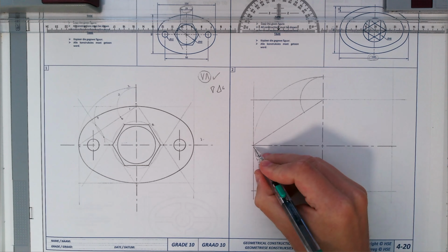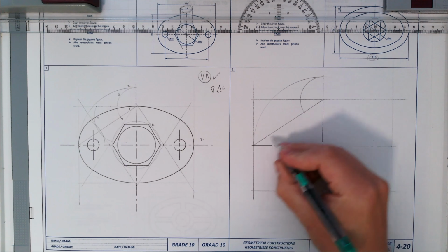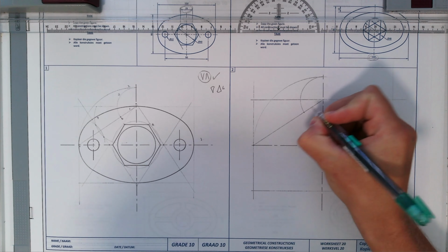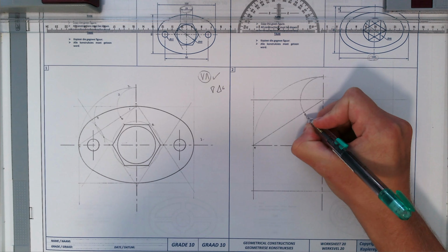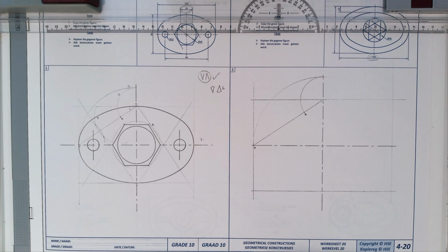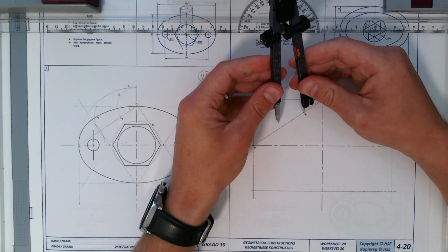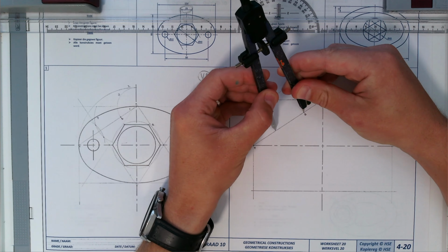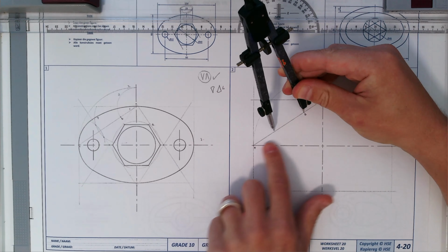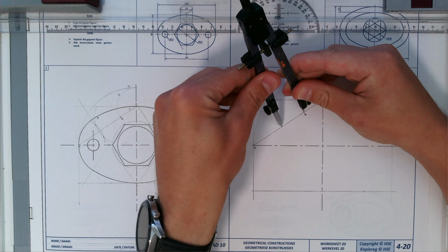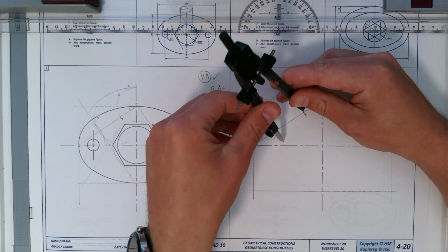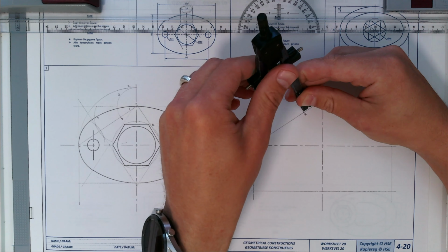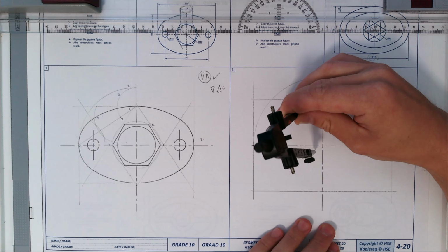Then what you want to do is divide this line perpendicular exactly in the middle. So we want to bisect that line. I'm going to call it AB. And the only way that you can do that is by using your compass. We are going to take the lead to more than half of that length. So the middle point will be about there. So I'm going to make it more than half, about there. So let's put it there. I want a bigger arc just to show you. So I'm going to draw an arc on this side.